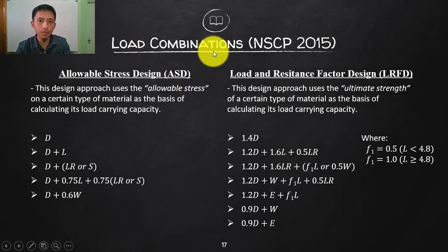Now, these are load combinations because we cannot say that the building is only under dead load. It is not only under live load. It is not only under earthquake, because, for example, earthquake is not there every time. So by using statistics, the combination is derived empirically, based on experiments and observations in statistics. A combination is made. So not every time there is a live load, not every time there is an earthquake, a snow, a wind.